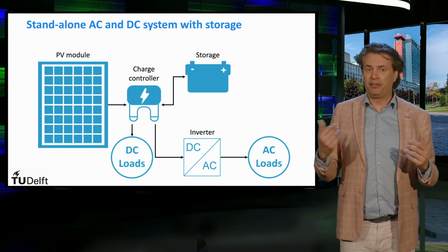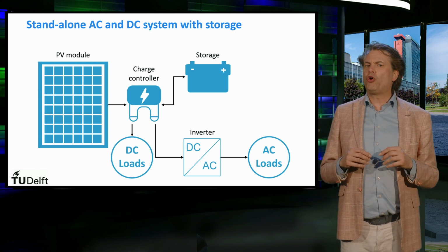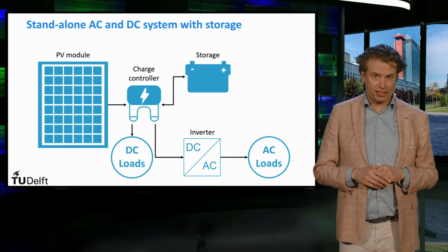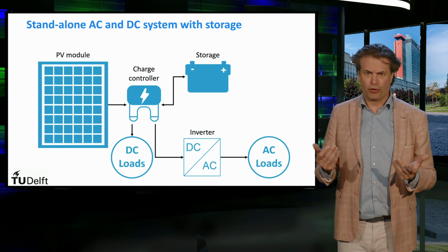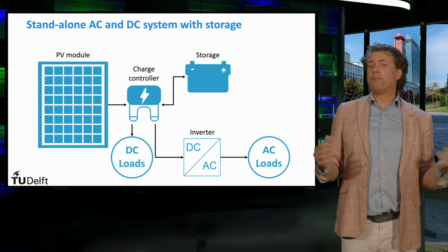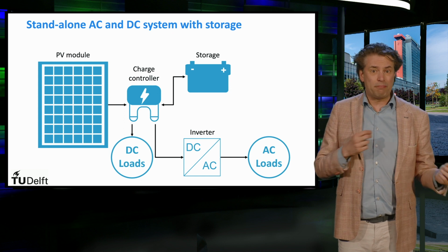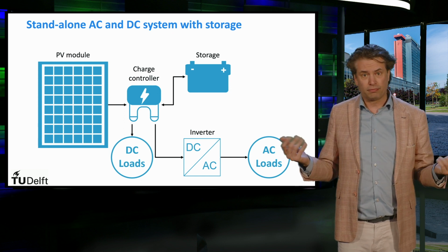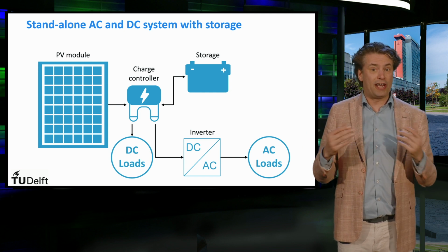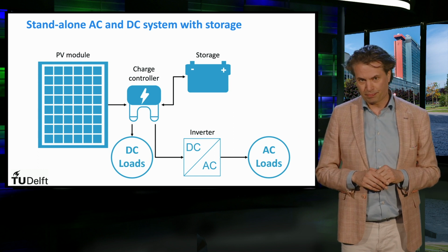This is the case of buildings that are completely independent from the grid. Note that in most modern houses, DC power is supplied directly to all the DC appliances without passing through an inverter, which would waste a lot of energy in the conversion. In addition, the batteries in these types of systems must have enough capacity to deal with the day-night mismatch between generation and consumption. Moreover, these domestic battery systems must also have enough capacity to face long periods of low radiation intensity due to weather conditions.